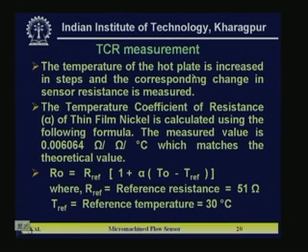For the hot plate heater, you can change its input power so that it will get more and more hot, and the sensor is attached to the hot plate, so the sensor temperature will also increase, and the resistance change is measured simultaneously at different temperatures.